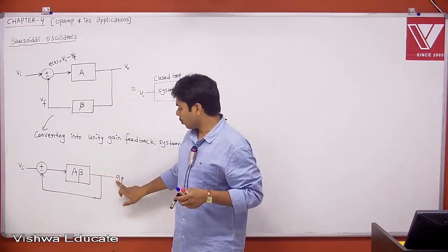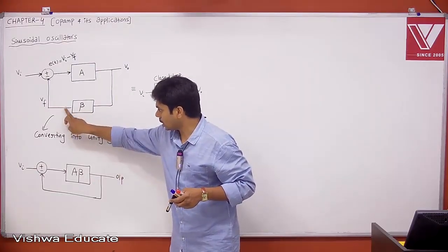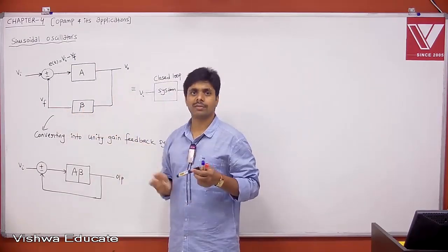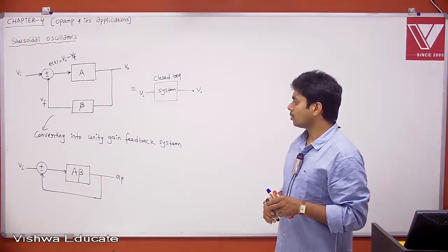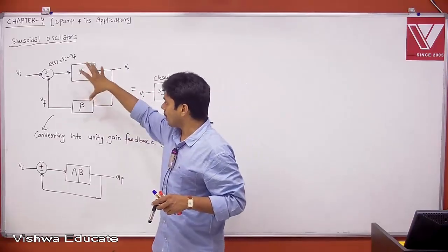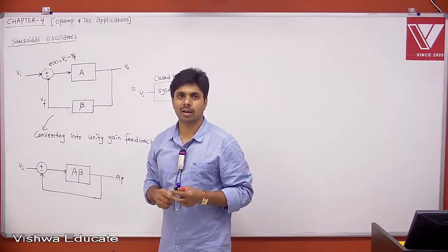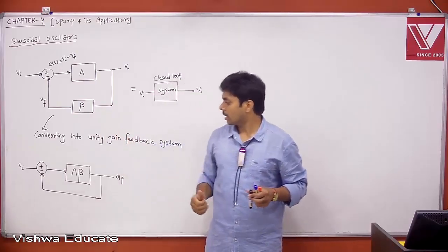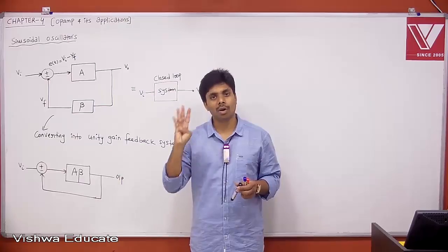Later on, if I know this voltage, indirectly it is nothing but the feedback quantity. If you know beta, can't you find V0? Yes, we can find V0 also. Now take either this or this, anything is fine, but ultimately we have to consider A beta, which is nothing but your loop gain. Then I'm going to consider this, and let me explain 4 conditions.